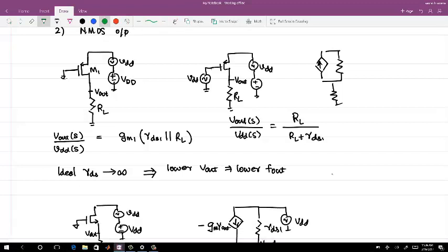Amplifier is giving the supply noise. You see, the noise on the supply of the amplifier is going to the output of the amplifier. If you use an input amplifier, then the supply noise on the amplifier is directly coming at the output of the amplifier, right? So if we use this case, then your gate is getting coupled to VDD with the amplifier, and the noise already exists on the source side of the PMOS. So then it becomes a resistive divider,